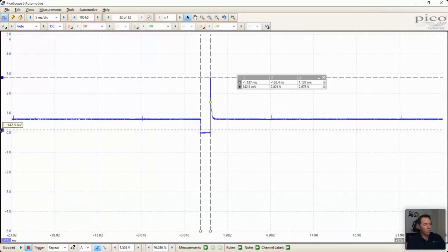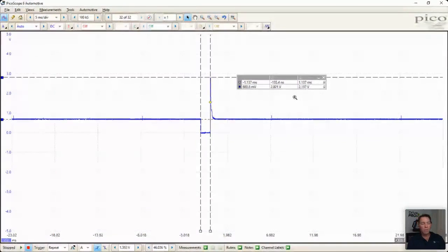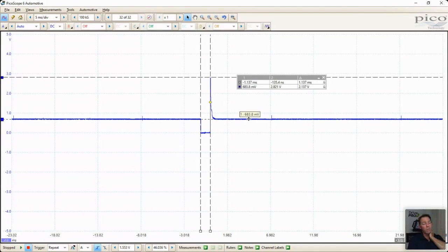Now if I move my rule 1 back up to my injector line, here it is. That's actually going to give me my supply voltage to the fuel injector. So if we see that here, that's around 600 millivolts on this particular pattern. And the delta between our on voltage and our off voltage is now measured over here at 2.13 volts. Now that's a bit unrealistic for a real injector. As we know, gasoline injection should be around 12 to 14 volts on this first line.